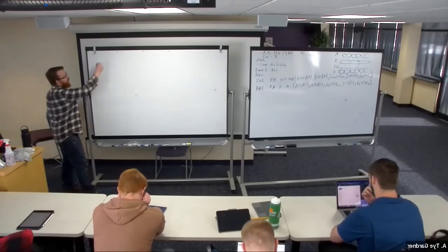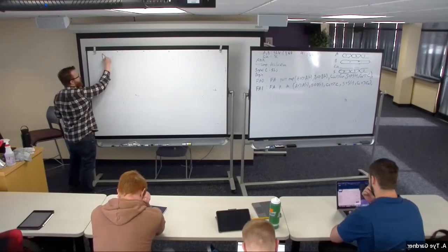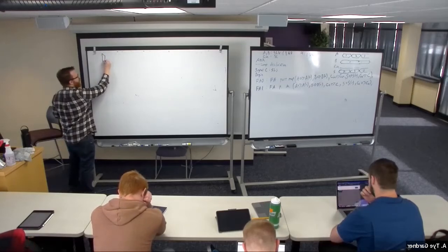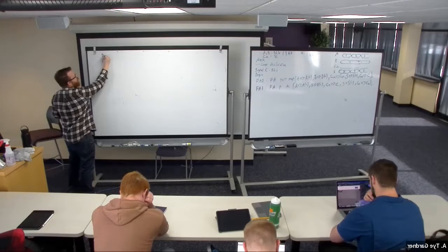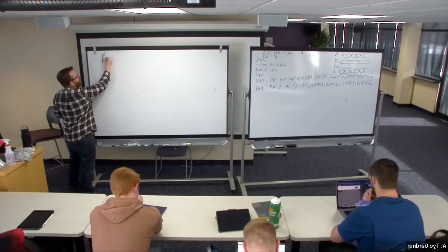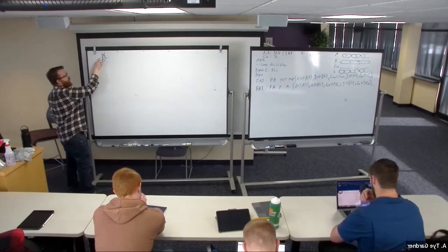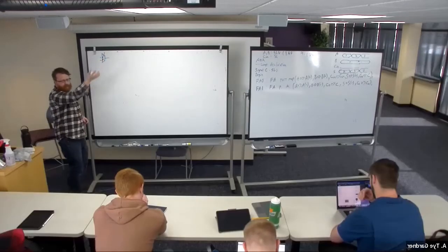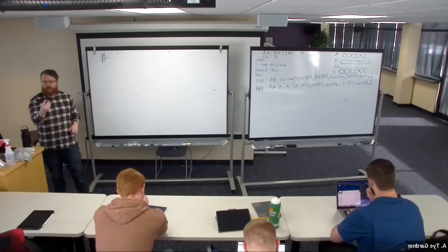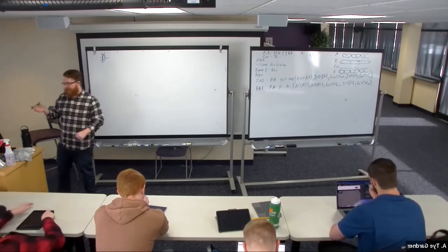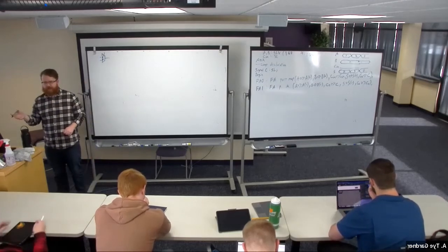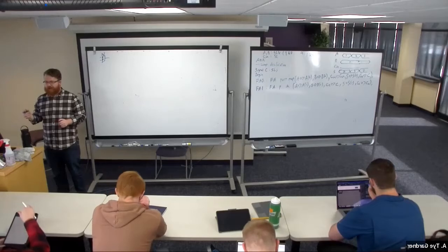Where we said that this is what a mux looks like. It has a select signal and 2 inputs, A and B. When select is 0, it takes A. When select is 1, it takes B and puts it in its output. And then hopefully you could go and draw a truth table for that, then write the logic.